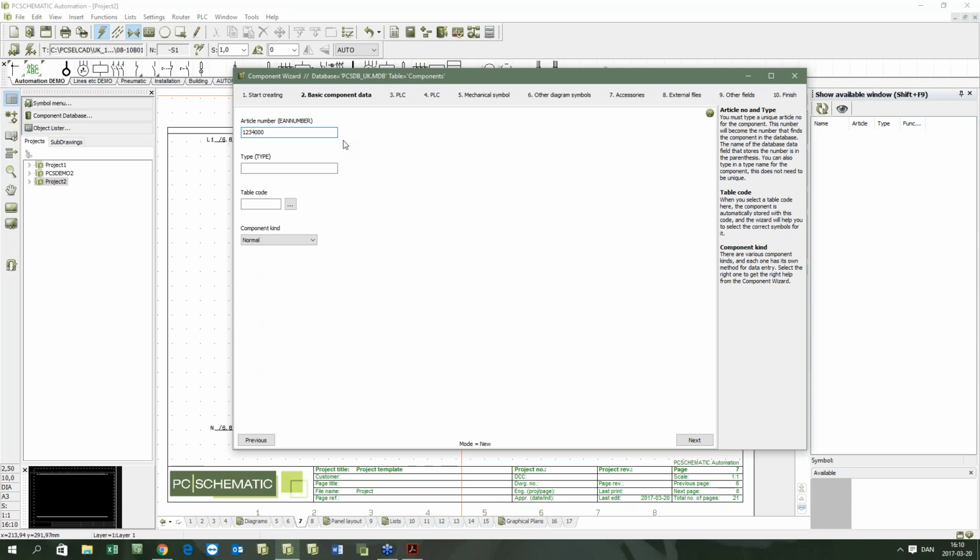This barcode number is not thick, thin. It's got a number on it, and you can see that if you have a component and you have the box, then you can see this barcode number, and this is a number that you can type in. Our normal barcodes anyway follow a standard called EAN 13. So if you type a number that fits into this standard, then the program can create barcodes for your parts list or components list.